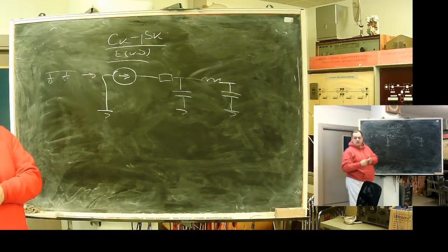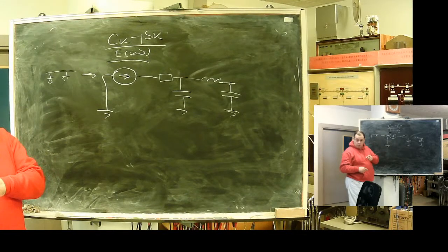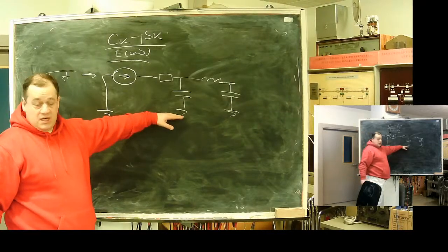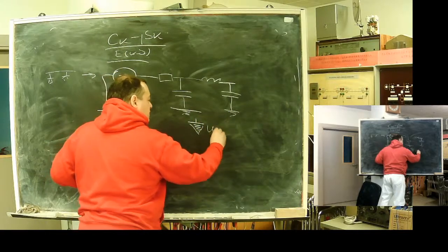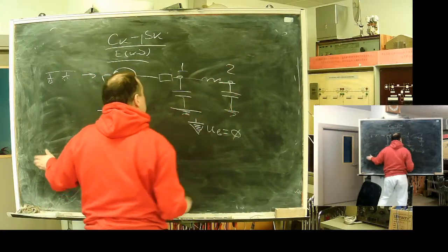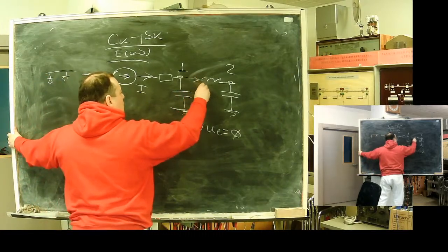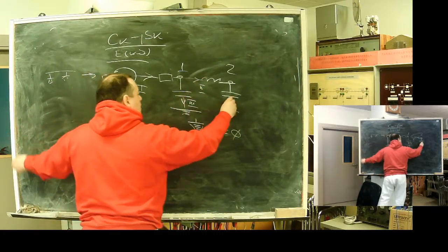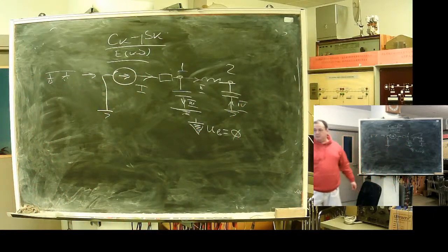What I need to do first, I need to assign numbers to all nodes and all branches. The only one accepting the base node. I have Earth here, it will be my base node with the voltage 0. All other, this for second and so on, and each branch will have number and direction. I need to specify numbers and direction for each branch in my schematics.